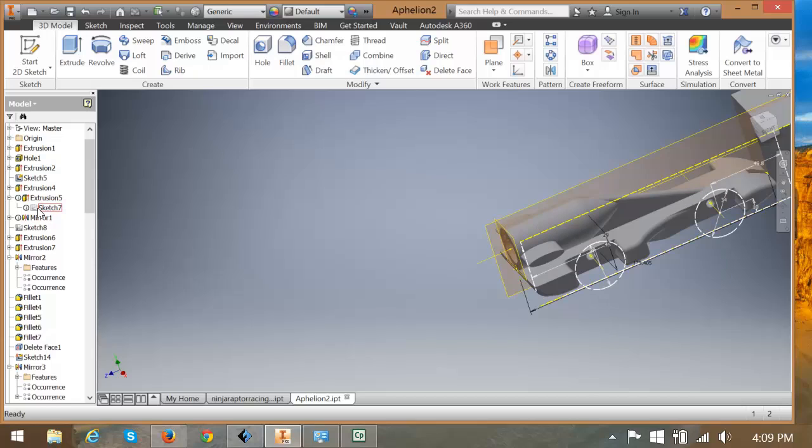That'll often be the problem, or you'll have something like an impossible bit of geometry, like you'll have a fillet that just simply can't go around where you want it to go. Get rid of those, fix them up, and then you'll have no problems. Okay, we've discussed most of the things we need to.